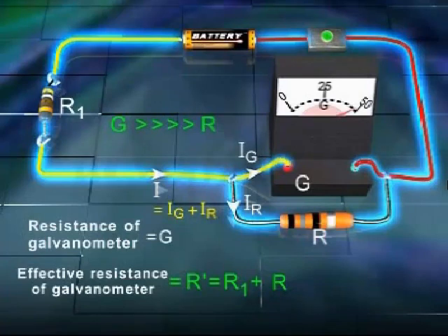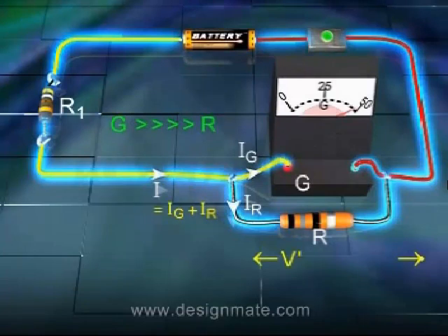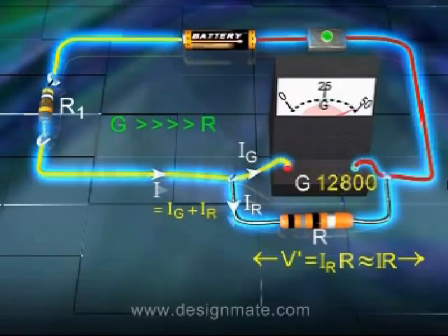Under this circumstance, the total resistance of the circuit does not change, and the resistance G being very high in comparison with R, almost all the current passes through R. So, the value of the potential drop IR across it also remains almost the same and is correctly measured. The discussion above shows that the device used for measuring voltages should have a very large resistance of its own.